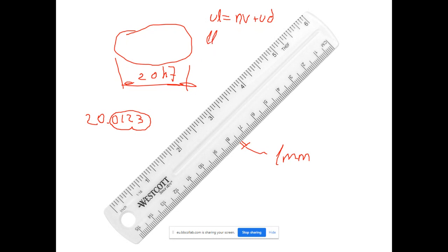Lower limit, one more time, see the expression: nominal value plus lower deviation, LD, lower deviation. Okay, well, you see here 20 is the nominal value, and say that this is the upper limit, for instance. This means the upper deviation in my example is 0.0123. Okay, this is the upper deviation. Can write a similar number for the lower limit, lower deviation.